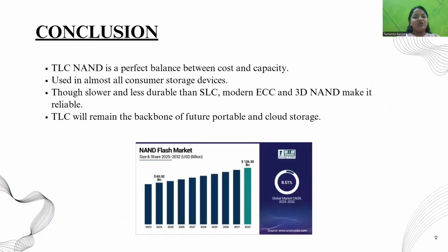So here I conclude my PPT. TLC NAND is the most widely used flash storage in consumer electronics. It provides the best balance of cost, capacity, and performance. Despite challenges like lower endurance and higher error rate, modern SSD controllers and 3D NAND technology have made TLC reliable and efficient in today's technology. With increasing demand for digital storage, TLC will continue to be the backbone of future storage solutions, especially for smartphones, IoT devices, and cloud storage.